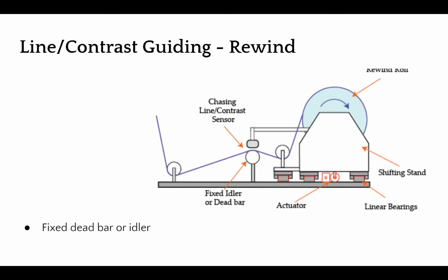Most often for clear films, ultrasonic sensors are used, but at 200C, the frequency of the crystal would be affected by it. So we might have to get back to you on that if we know of any sensor that can be used at 200C. There are some other questions that are specific to our product, which we will answer separately.